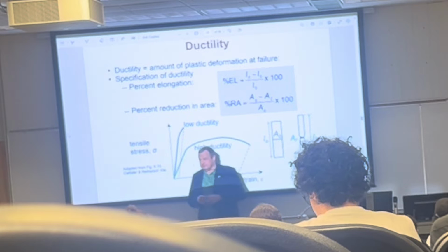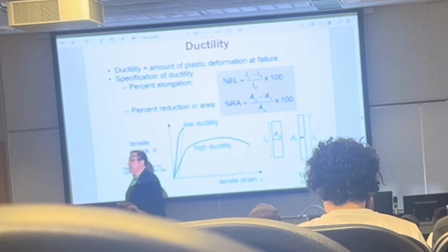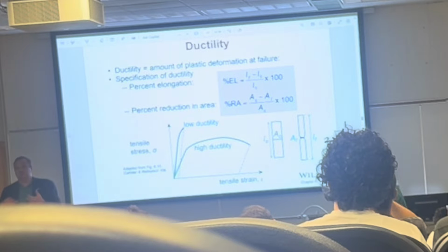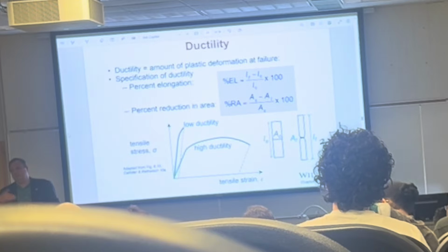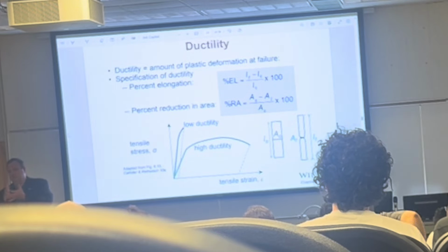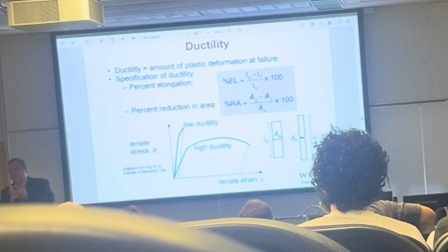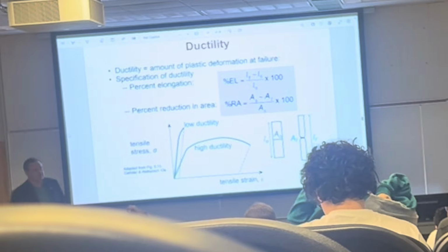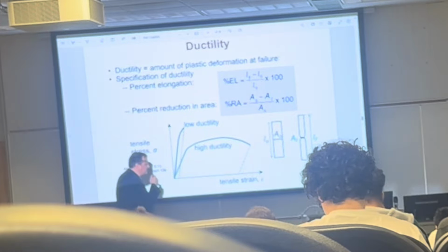This necking only happens by shear, and now you see a demonstration of how one type of loading, uniaxial tension, is causing shear on planes that are not aligned with the axis of the applied load. Any plane is going to have a projection of the force, and that's going to cause shear. Any questions about this?